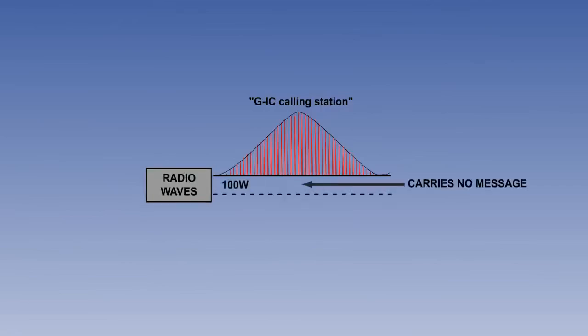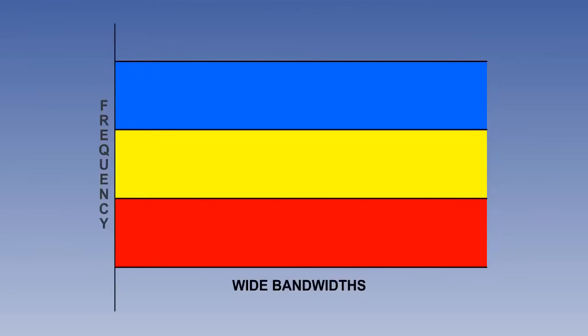Similarly, the radio wave, having served its purpose to get the audio information into radio frequencies, is now redundant and should be either reduced or suppressed completely. In addition to the power saving, it is desirable to reduce the overall width of the transmission because skywaves are liable to distortion in the ionosphere. The narrower the width, the less the distortion and the better the signal-to-noise ratio.